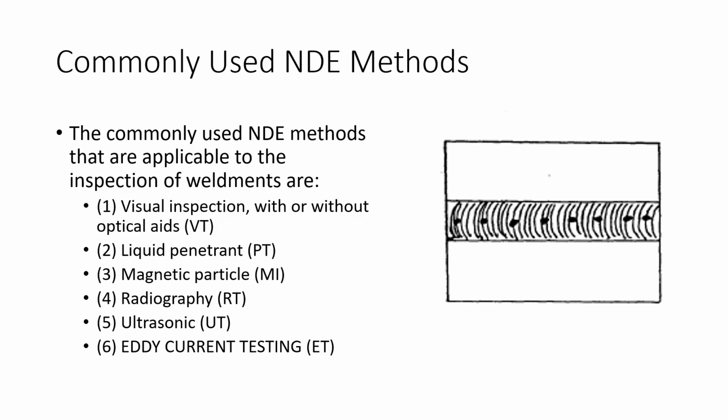So once again, we talked about the commonly used NDE methods. We've got visual inspection, with or without optical aids, liquid penetrant, mag particle, radiography, ultrasound, and eddy current testing. These are the common ones that we're going to talk about. There are other ones that are way more specialized, but for the normal universe within welding and materials manufacturing, these are the big ones, the most commonly utilized